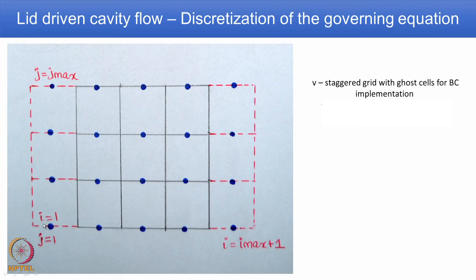For simplicity's sake, we define the delta x of the ghost grid line and ghost cell the same as the immediate adjacent cell. Similarly, for the other direction, because V is in a staggered grid arrangement, they are all stored along the horizontal line and are shown in this picture with a full circle.